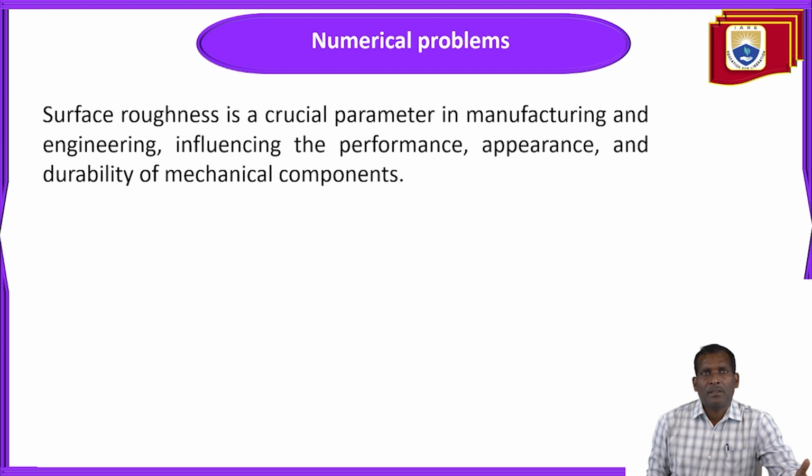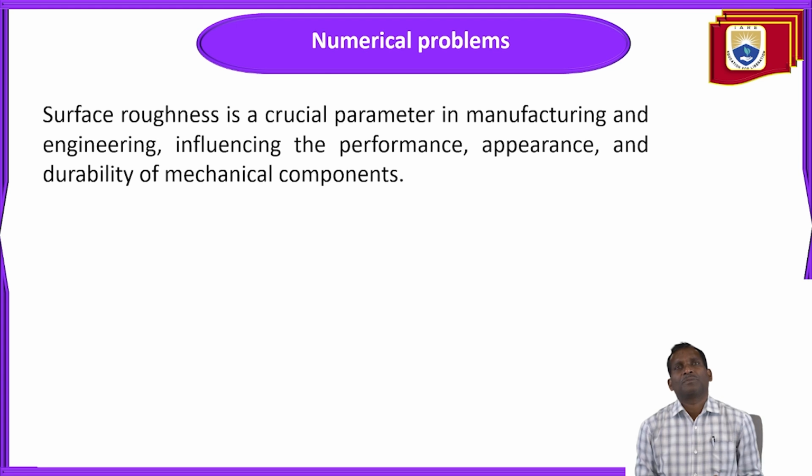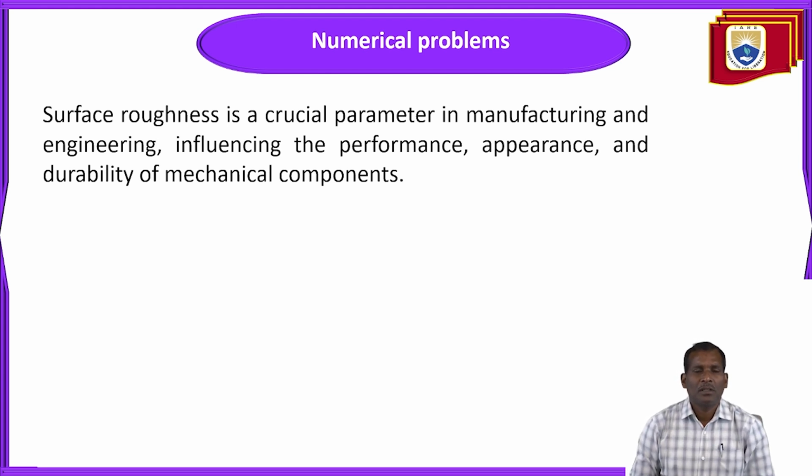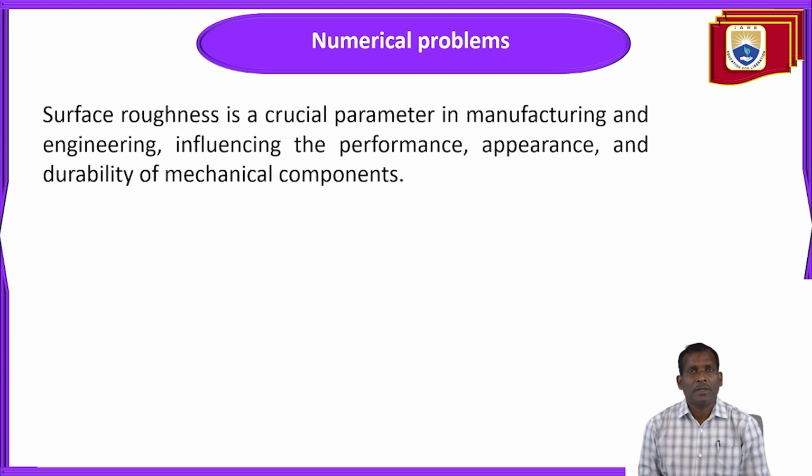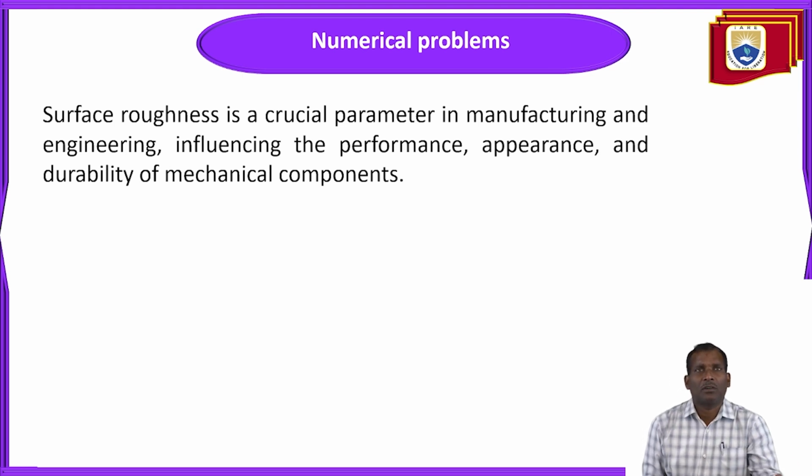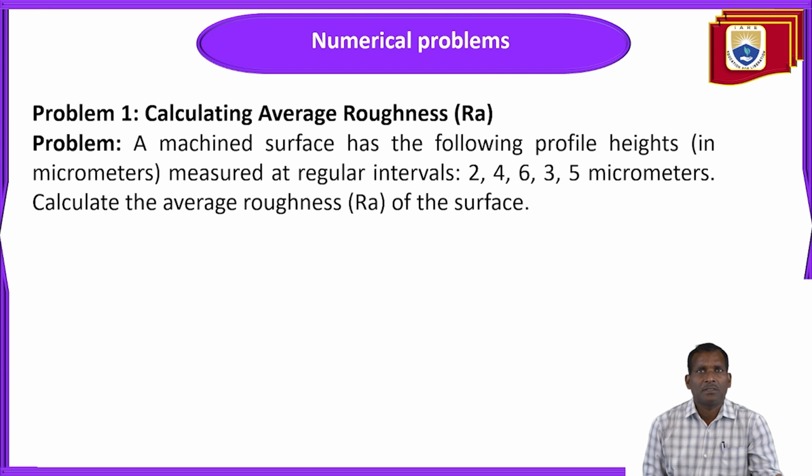If the surface roughness is good, the product will perform with high efficiency. Why? Because less wear and less friction will be developed. And if surface roughness is good, the product appearance also will be good, and durability also will be increased. That's why all mechanical components require surface roughness.